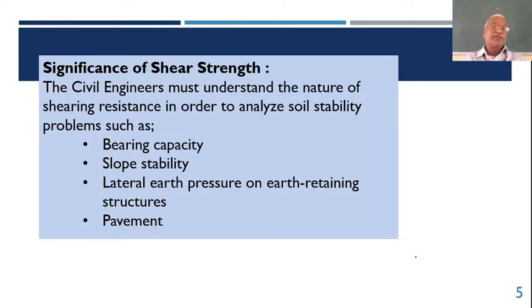Okay, significance of shear strength. Why should a civil engineer study or know the shear strength of the soil? Civil engineers must understand the nature of shearing resistance in order to analyze soil stability problems, where all the stability of the soil comes into the picture. It is bearing capacity of the foundations, slope stability, lateral earth pressure on earth retaining structures, and then the pavements, right? So these are the situations where we should know the shear strength of the soil.